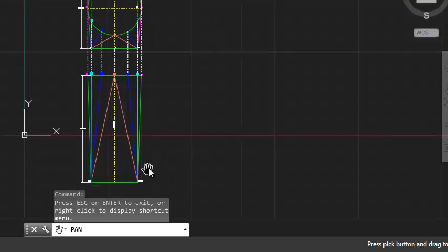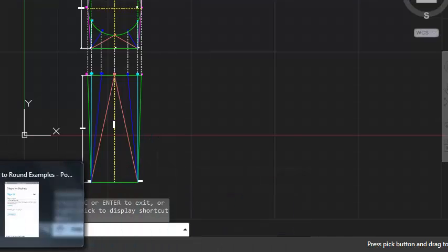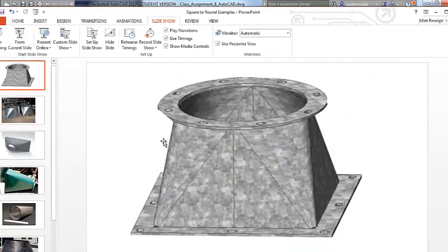So on your screen right now you're seeing we're going to be working with two views again. In the last several series of videos, we've been doing front views and right side views, mostly. So now I'm going to keep my front view, I need that too, but now I have to have a top view. These two views are going to talk to each other and get us the information we need to actually pull up true lengths. So I'll mention one more thing back to my PowerPoint and the very first one.